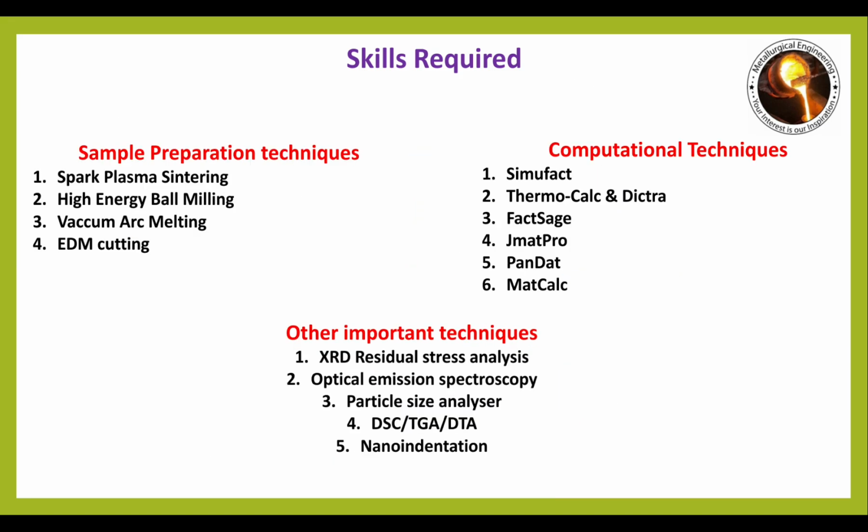Now we have another thing, sample preparation techniques. If you have decided this material is useful for this application, how can you prepare it? You can prepare it through vacuum arc melting in the lab, or through ball milling plus spark plasma sintering. So these are a few techniques for preparing the samples.